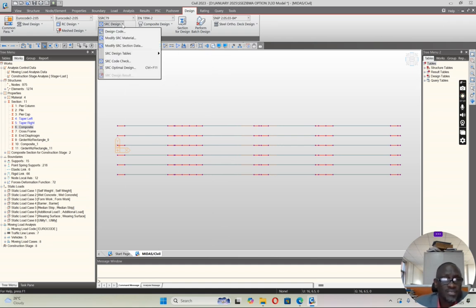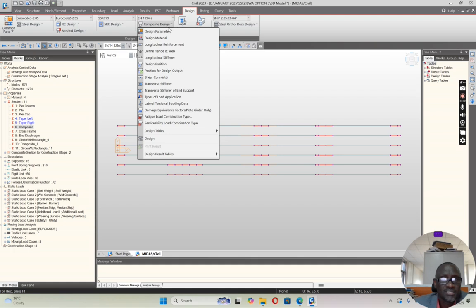Then I go back to the command tracking, continue coming down. You have the defined flange and web. Here it's already defined longitudinal stiffeners. When the steel plate girders are deeper than a certain depth, then you need a longitudinal stiffener. But this is, I think, 1 meter, 1.2. We are about 1.2. That is not as deep as we could, but still, if you want, you can specify.